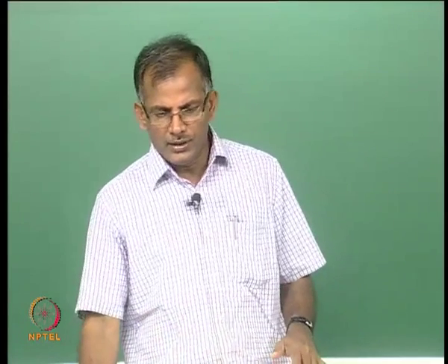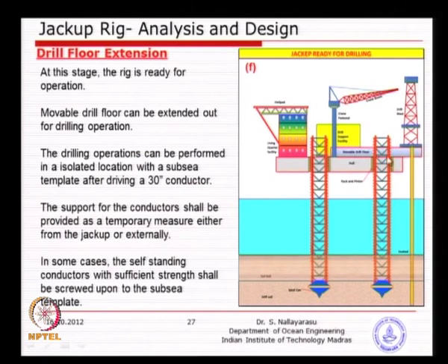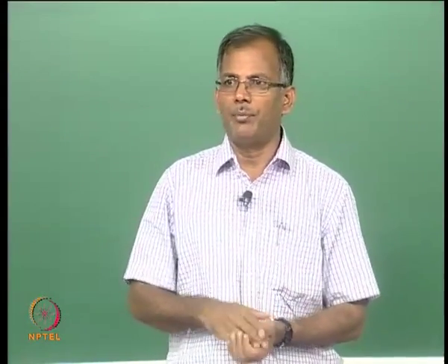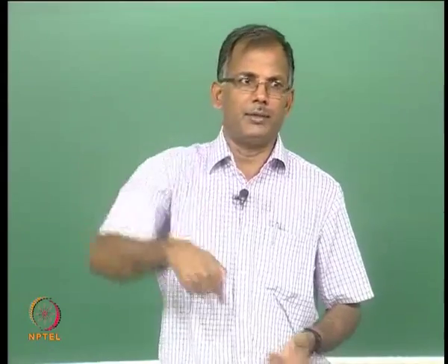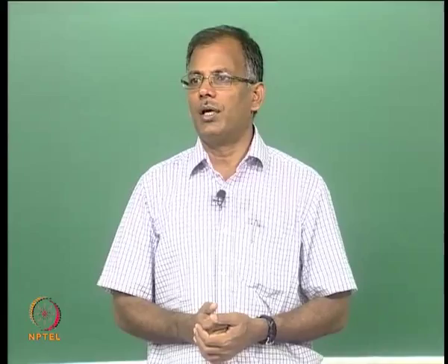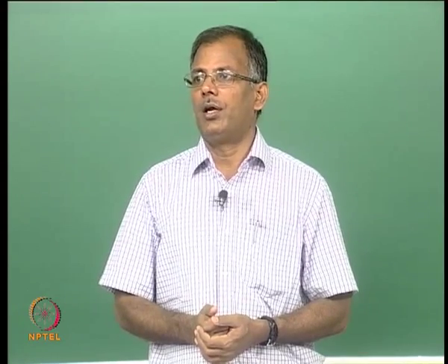So, you see here in this particular case, this drill floor has just moved away from the edge of the jackup, allowing the drilling to happen. Now, you see here, when you are trying to do drilling in open sea conditions, there is no jacket, no structure, and the water depth is 50 meter, 60 meter, 70 meter. So, you have to be a little bit careful, because the drill bit goes directly into water. What will happen? The drill string gets broken, because sea conditions are not very good.